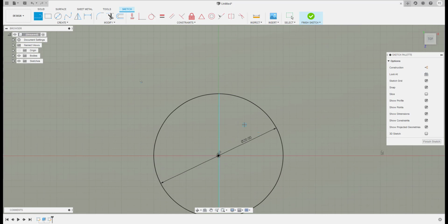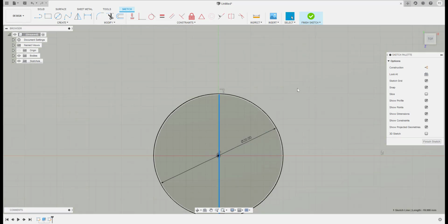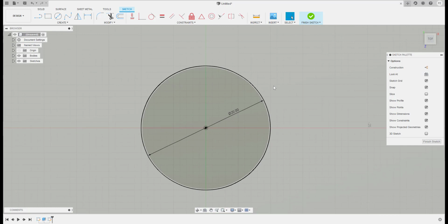So I'm still holding this line tool. I'm going to press escape twice to get rid of it. And then I'm going to select the line that I drew and press the delete key on the keyboard. The delete key is not the backspace key, okay? So don't press the backspace key. That doesn't do anything. It might, but last I checked it didn't, but it might.